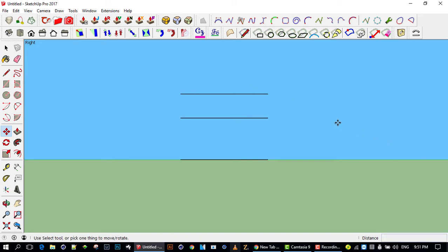The other way of doing it is if I had to select this line and I go move tool, press control, I move it up over to the final area, and then I say divide by 3. So it's going to put basically lines in between the one that's originally and the end one. So divide by 3, press enter, and then it puts those lines in. Okay, so it says divide, and it's going to add 3 lines.